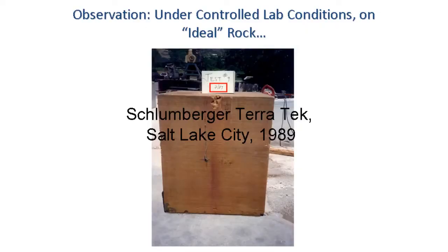That's called validation. It's a very important concept in engineering. Anybody can write down an engineering model or theory, and it's worth nothing unless it can reproduce what you can see. That's called the validation process. So it's always necessary to do physical experiments to show that your computer models have merit. So we drilled a hole, just like the movie said. We put a casing in it, steel pipe. We cemented the casing. We perforated the casing in the cement and the rock, and then we injected colored fluid as pressurizing hydraulic fracturing fluid to see how the cracks evolved over time.